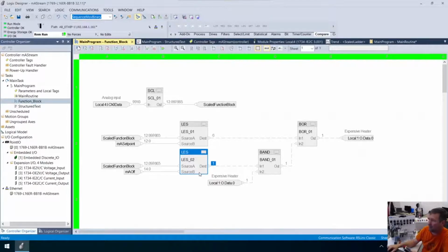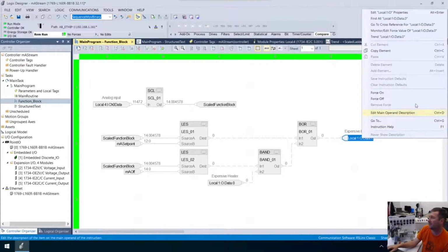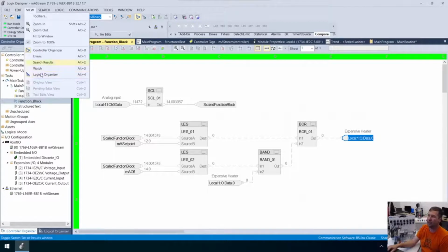And we're going to cycle through this exactly the same as we cycled through with our ladder diagram. So they're going to do the exact same thing. And I had these set up down there where we had brighter things and we could have shown all of them at the same time, but you get the idea here. In fact, yeah, I can do a watch window. So let's right click this and, oops, I wonder why they don't have a watch option there. But okay, at any point you can go to view and you can go to watch.